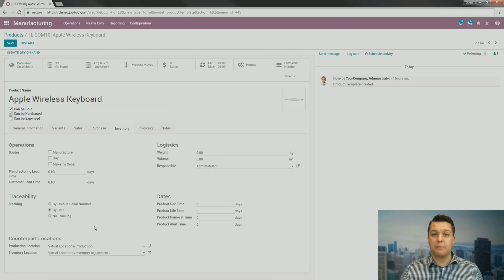So you get something from one of your vendors, the second you first actually have hands and eyes on the product, you'll assign a lot number to it, and that is going to live with that component throughout the whole process. So when it goes into inventory, when a new manufacturing order comes in, and you want to pull some of that inventory for a specific manufacturing order, it's going to ask you what lot and how much are you pulling. This kind of traceability won't let you do that operation without identifying the lot, so it kind of combats human error, let's call it, in terms of losing that traceability through the process.